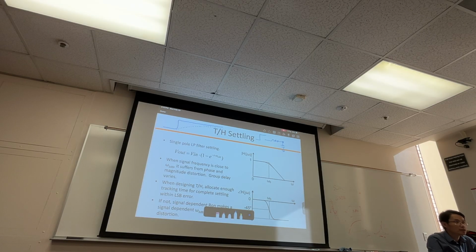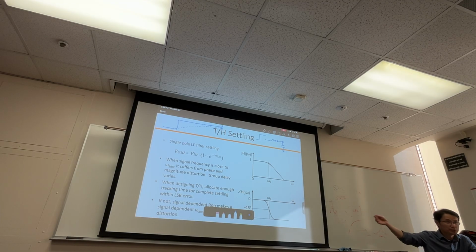You want it to go up instantaneously, it will take time, and then gradually it will catch up. Actually, do they catch up? It never catches up. So unfortunately, as much as we hope, that's a sample and hold, right? Supposedly you should sample the exact value. In real life, there's no such thing. There's always a tiny bit of error right here. So first of all, do you agree that this error will go down as you give more and more time for the tracking? It does, right?